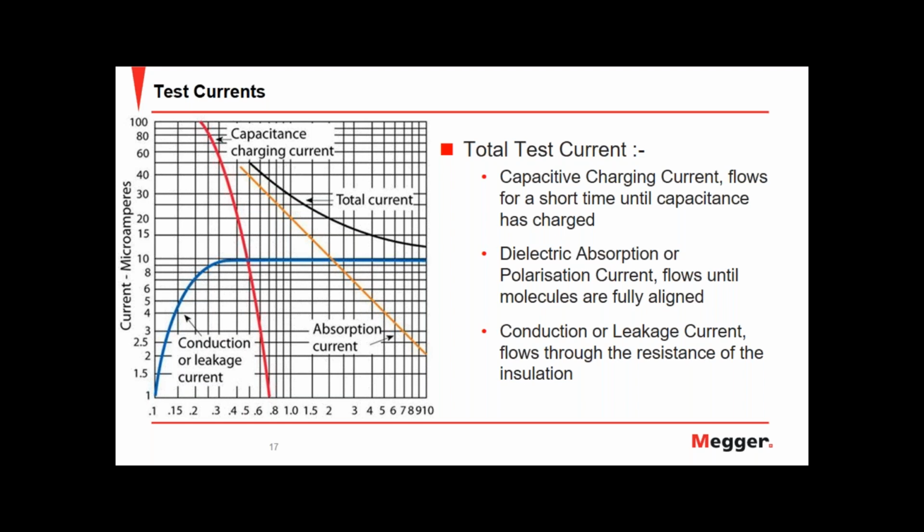But one of the things you need to be careful about is that, depending upon what type of insulation that is, either epoxy mica or some other form, each of them has a different volume resistivity. And what that does is that the rate of polarization, the rate of change of field distribution, is going to be different for different types of dry type insulation.